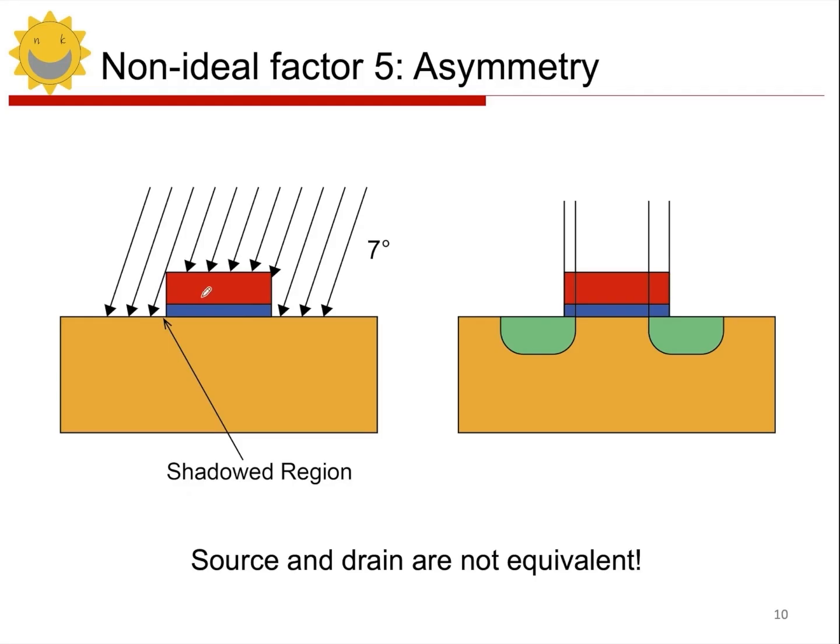Imagine a wall with light shining on it, creating a shadow where light can't reach. Similarly, for the ion beam, the gate creates a shadow, blocking ion implantation in that area. This causes different overlap regions with the gate. As a result, we see a phenomenon where the overlap of the two implantation regions with the gate is different. On the right side, because the entire area can receive ion implantation, the overlapping region will be larger.